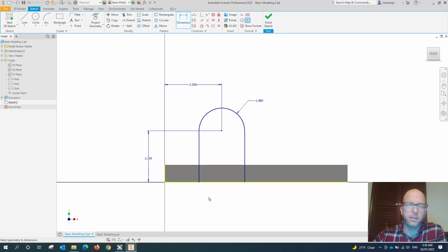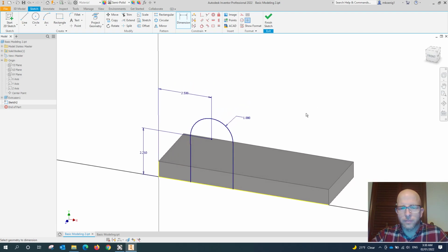So when I clicked to make the line coincident to that edge, it just converts that edge into a sketch entity. So they're just yellow, showing that it's attached to that extrusion. It's not something I sketched. So if we alter this extrusion, this yellow edge will move with it, and our sketch will move as well because it's coincident.